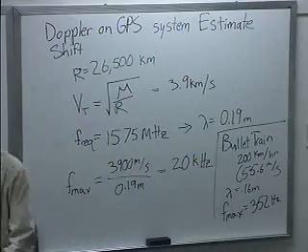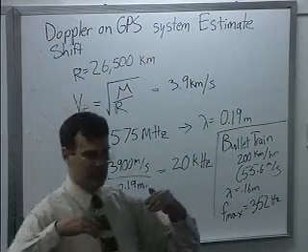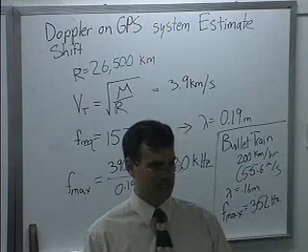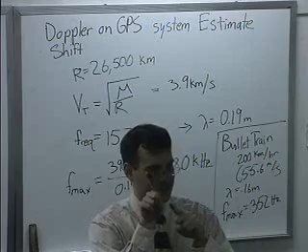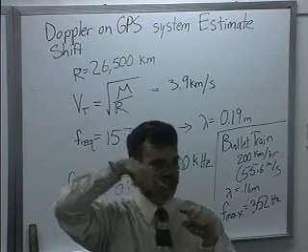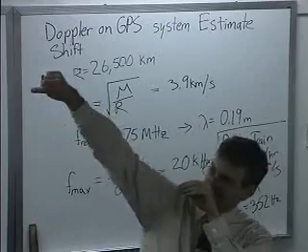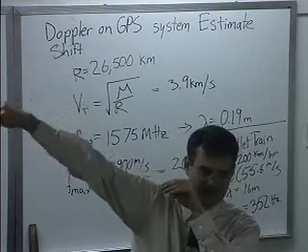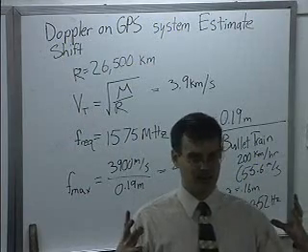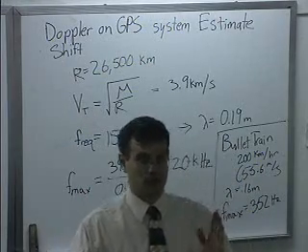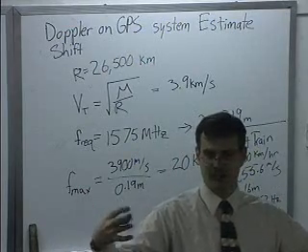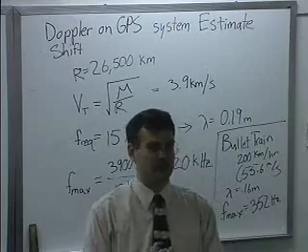Now, keep in mind that for our GPS signal, we didn't estimate any geometry effects in this. Chances are your satellite is never going to be going exactly away from you or towards you. The worst case scenario is probably when it's in its circular orbit on the horizon. But also remember, this is an estimate of maximum Doppler displacement, so this could be up or it could be lower. And so about twice that could be the conceivable range that your system would have to operate under.